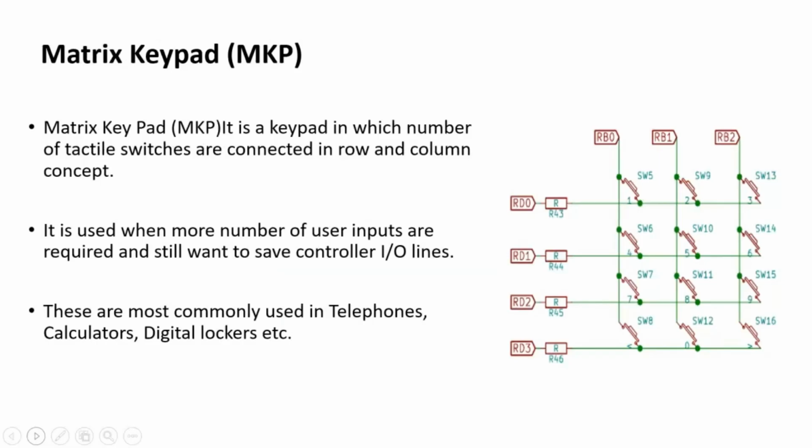Matrix keypad. Matrix keypad is a keypad in which a number of tactile switches are connected in rows and column concept. It is used when more number of user inputs are required and we still want to save controller I/O lines. These are most commonly used in telephones, calculators, and digital lockers.